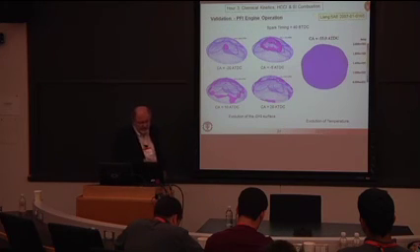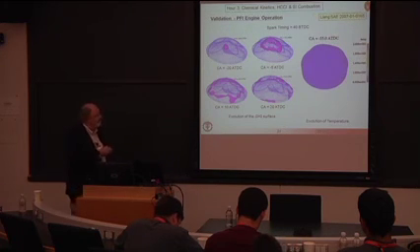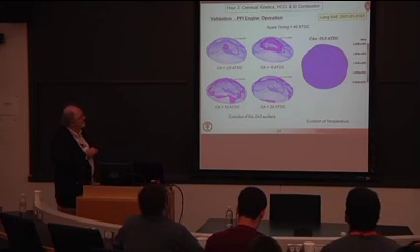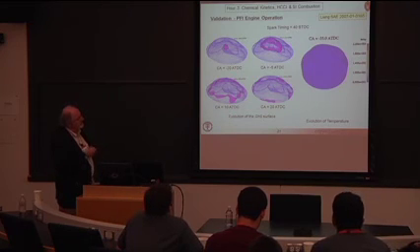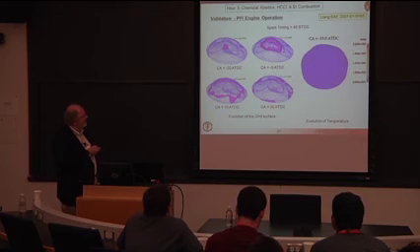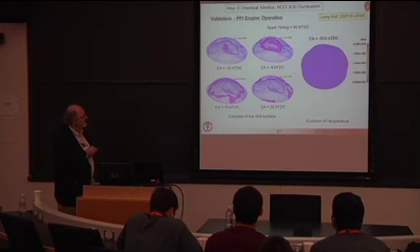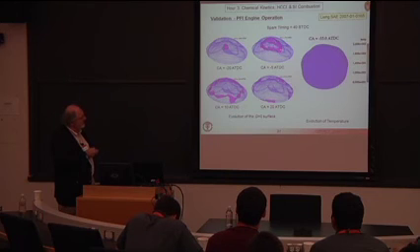Here you can see a picture of the domain. It's a pent roof engine with 4 valves. You can see that here. Here's at 20 degrees before top dead center, for the case where we spark timed 20 degrees earlier than that. Here's the initial G surface. The spark plug is located in the middle of the chamber. You can see it at 5 degrees before top dead center. The flame has propagated quite a distance. Here's at 10, here's at 20.